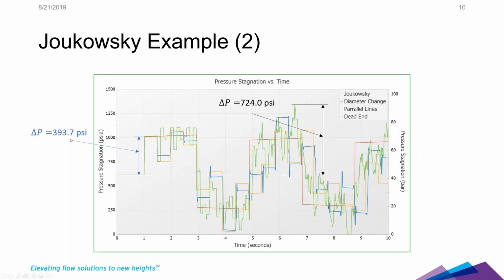We can see that the initial delta P is exactly the Joukowsky pressure rise, okay? But that's the red line. So that will oscillate back and forth given the kind of typical Waterhammer example, single valve reservoir, instantaneous closure. There's a good example of that in the Impulse help file where you can see all of the behaviors at each interval of L over A. But what we're seeing here is that at the diameter change, we see some partial reflections, and oh, that spike's bigger than Joukowsky. It comes back and it has this funky oscillating behavior.